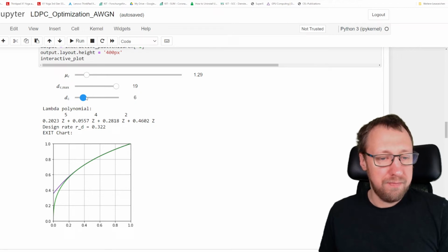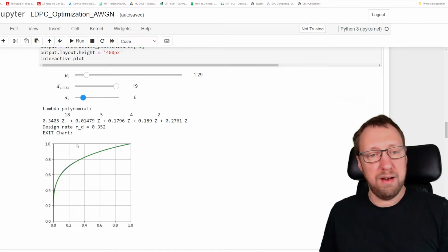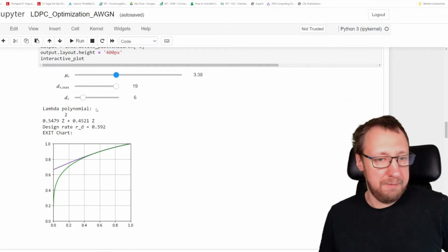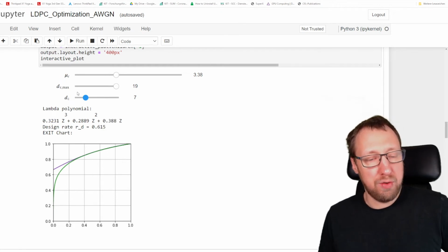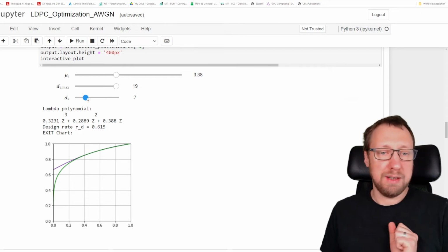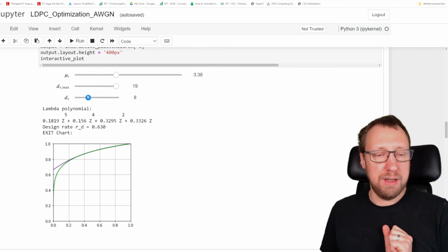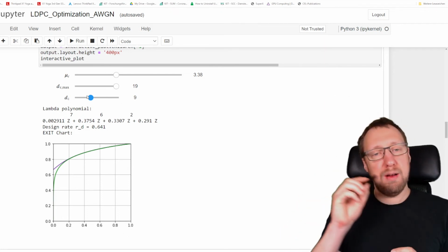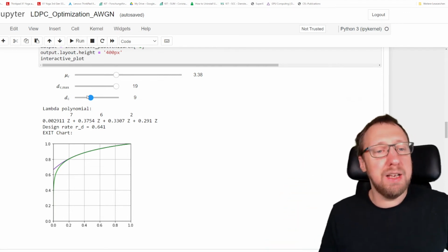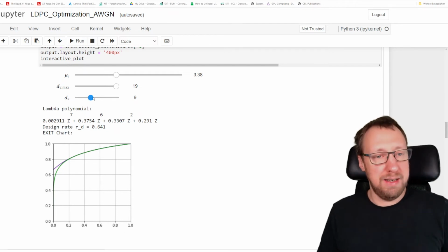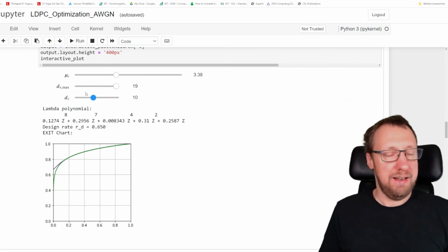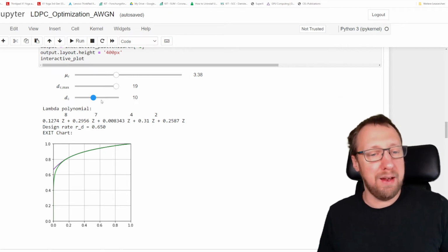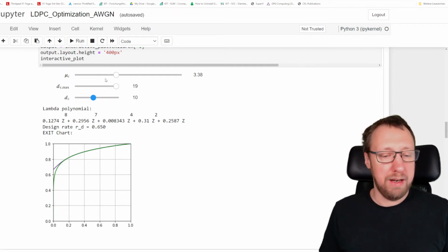If we increase the check node degree, then the check node curve will move up and the code will become again more challenging. But if we increase the channel quality, we'll have some space again. Here we can crank up a little bit again. And you also see if we crank up the check node degree, the rate will also increase. This is a byproduct. Increase the DC, and you'll see an increased rate, because the rate is 1 minus DC over sum of lambda i d_i. So if we increase DC, we also increase the design rate. Actually, it's 1 over DC that's inside here. So we can play around with this a little bit and get a feeling for the different parameters, how the EXIT curves change and how everything changes in here.